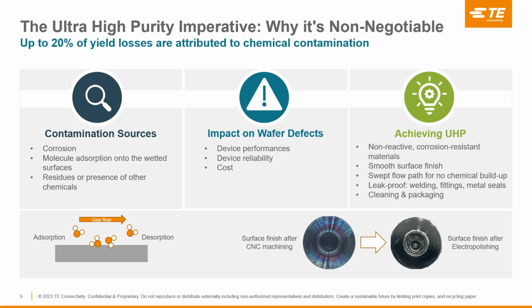The byproducts of such will have consequences on the surface of the wafer, which are likely to lead to yield losses. Another reason is in fact a phenomenon where the molecules adhere to the surface due to its intrinsic porosity. This is called adsorption, and even if the effective quantities are very small, down to molecular level, the risk is that the same molecules can be released at any time, which can lead to an unpredicted event, and ultimately affecting the process negatively. This is linked to the previous point where there are unwanted chemicals entering the process chamber.